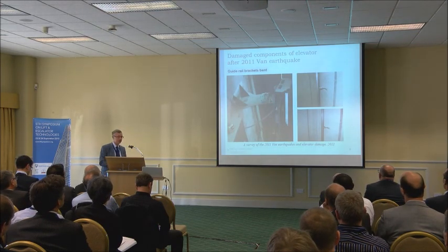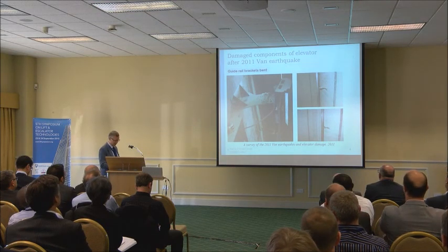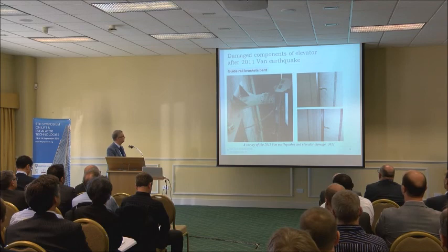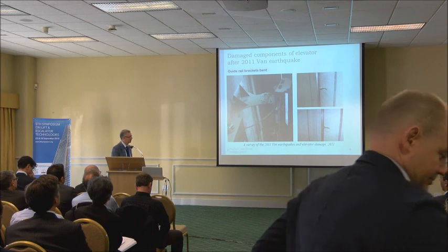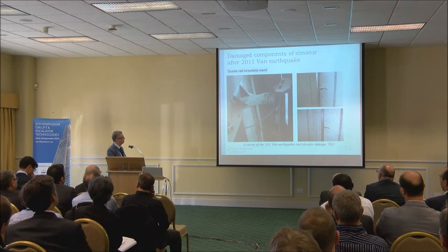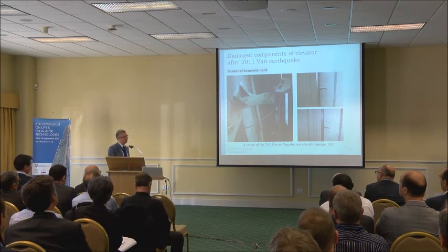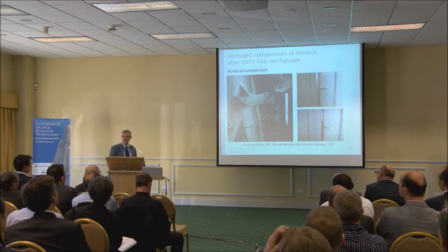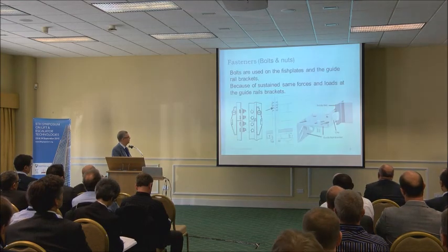Well, when we looked inside the shaft, we observed that almost all elevators had guide rail fastening systems, mainly brackets, that were bent, and some bolts and T-clips were cut because of this seismic force or other issues. So we started to focus our work on this issue.